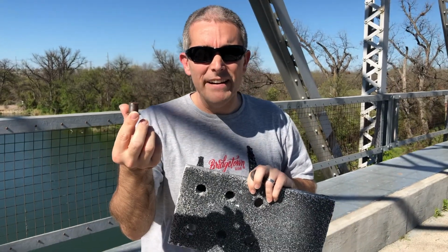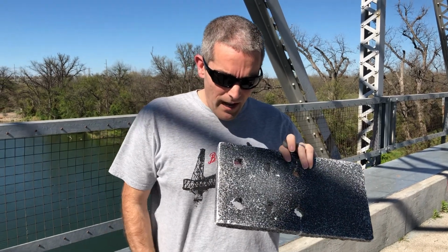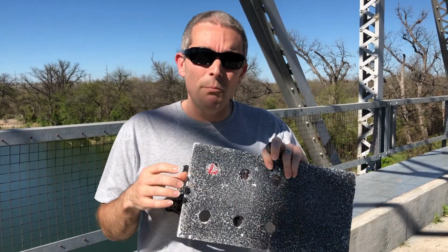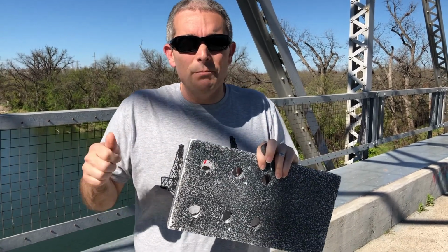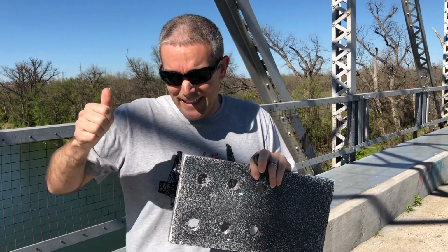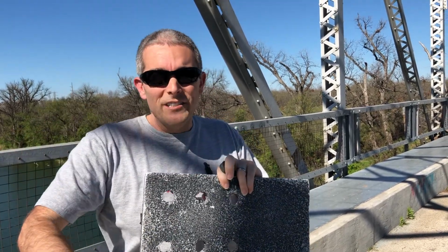But this is not very fast to do for design. So a lot of times for plate members like this, we'll punch them. Think of just like your 3-hole punch that you punch for your papers, right? You have a die and you have the punch and you just drive it through.